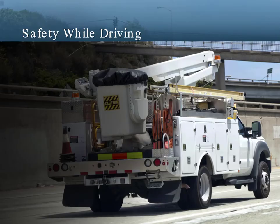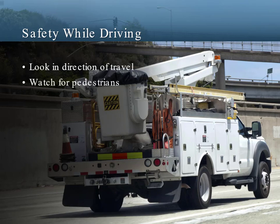Of course, safety is also an issue when driving a vehicle equipped with an aerial lift. Always look in the direction of travel and keep a clear view of the path of travel. Watch out for pedestrians. Maintain a safe distance from any ground obstacles such as debris, holes, depressions, ramp edges, and other hazards.